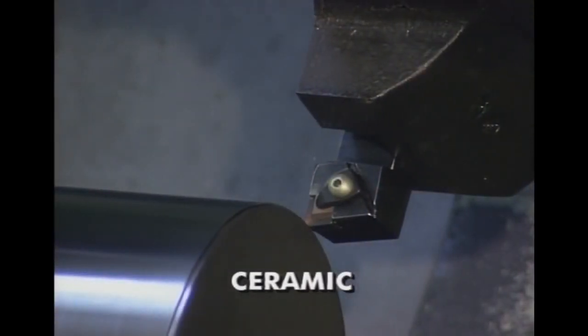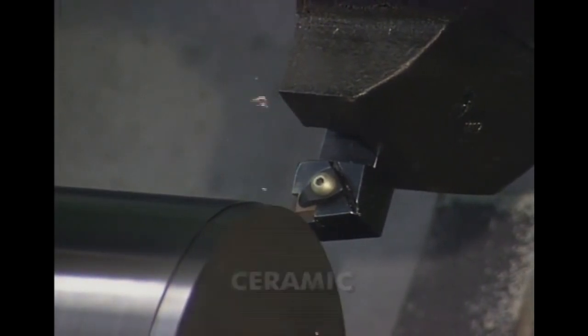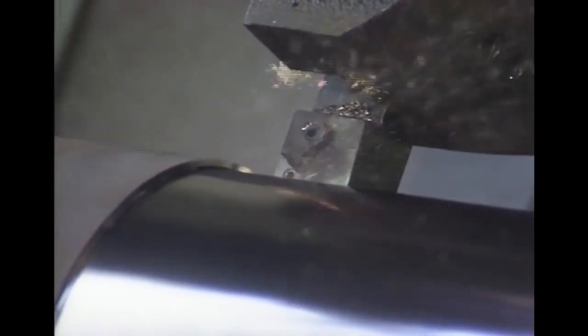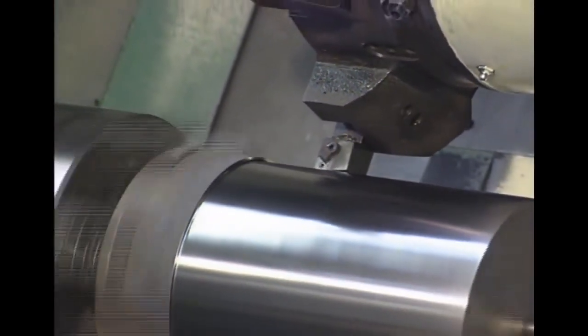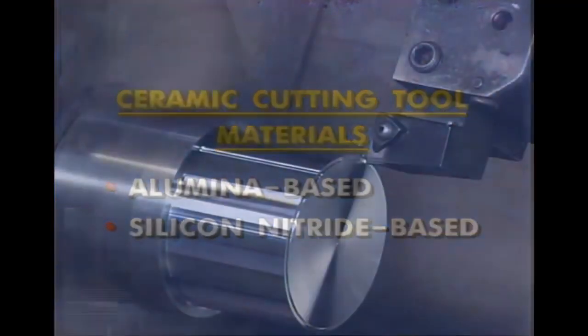Ceramic tools are harder and more heat-resistant than carbide tools, but also more brittle. They have been successful in machining cast iron, hard materials, and superalloys. Best results are at high speeds, which mean high cutting temperatures. Ceramic cutting tools can be divided into alumina-based ceramics and silicon nitride-based ceramics.